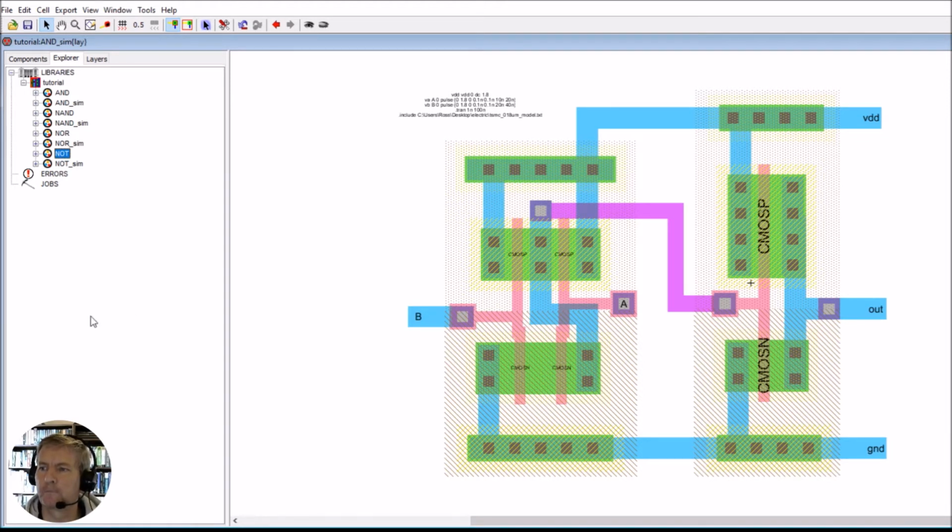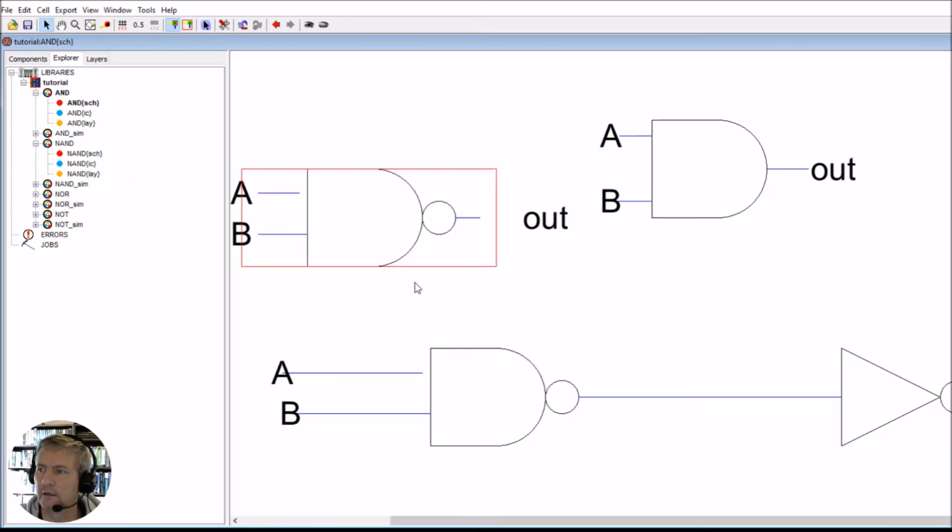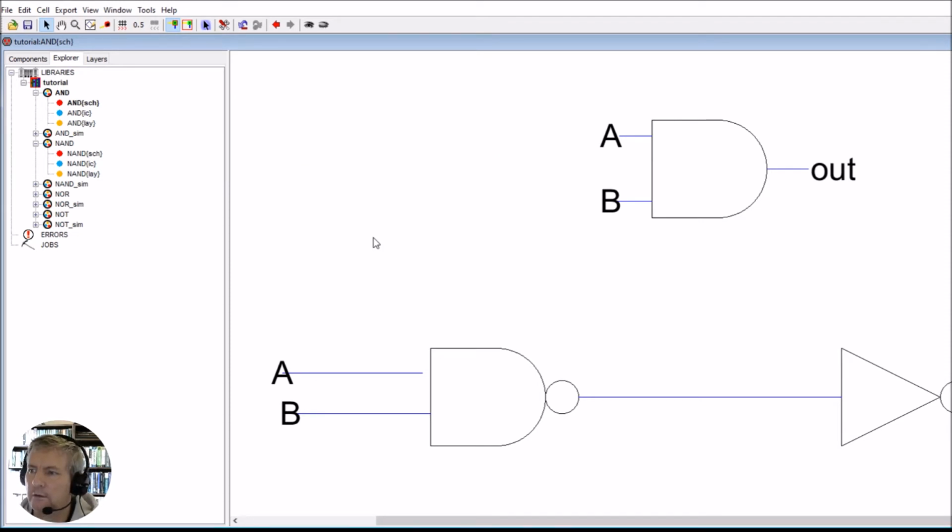because we just want to refer to the actual Boolean logic. So in order to create the AND gate, we can create an AND gate using the NAND and then put the inverter after it. When I went in to create this schematic, I can just pick out the NAND schematic here. So this is the NAND here. I can just pick out this, which is the actual icon, and I can just place the icon. If you wanted, you could place a schematic. It's up to yourself, schematic or icon. So I placed the icon here, and then I placed the NOT icon.